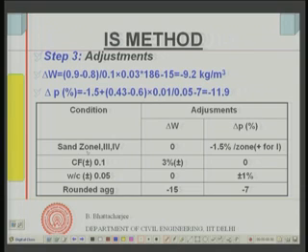Now, our sand is zone 3 sand, and the water cement ratio for the basic table is 0.6, while our water cement ratio is different, 0.43. So, there we will have some corrections here as well. We also have compaction factor 0.9, whereas the table had compaction factor 0.8, and our aggregate is rounded aggregate. Therefore, we will have corrections in both delta W, that is water content, as well as the volumetric proportion of the fines.